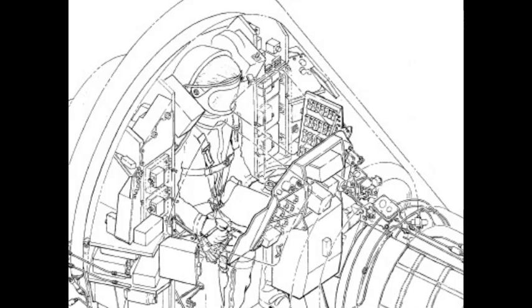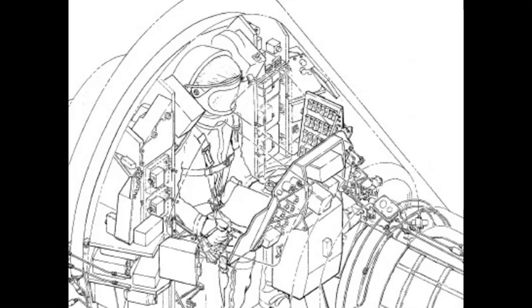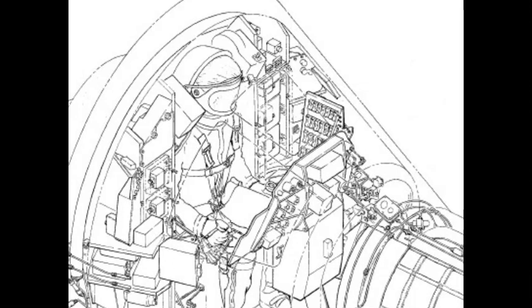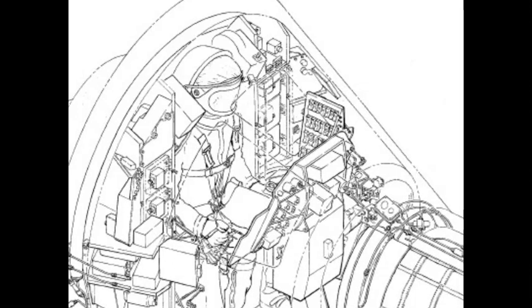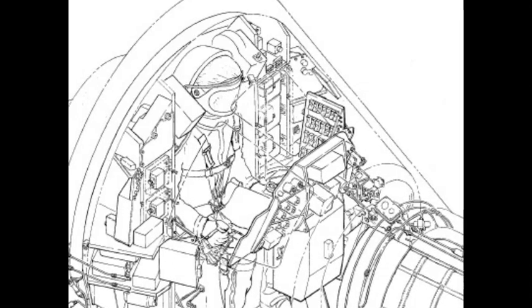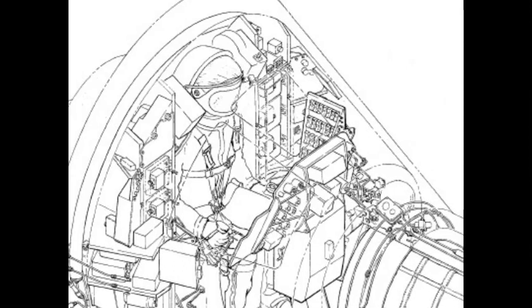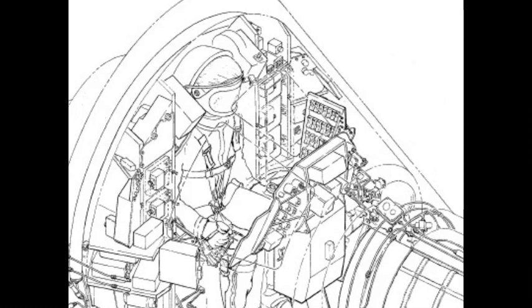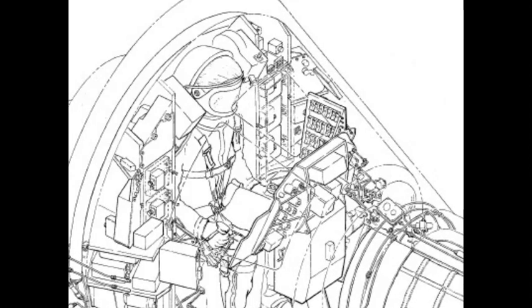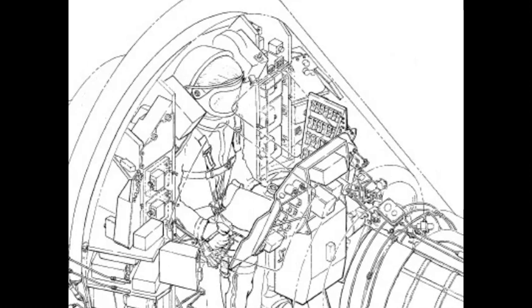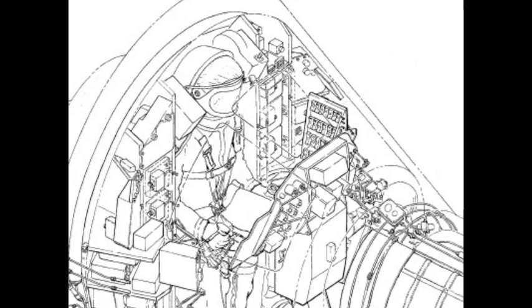2.10. The large pressure bulkhead supports the forward end of the conical section and internally separates the pressurized cabin from the forebody heat shield. The large pressure bulkhead is constructed of a combined inner and outer titanium skin. The outer skin is beaded and seam welded to the inner skin. The bulkhead is reinforced with horizontal channels installed on the outer skin.